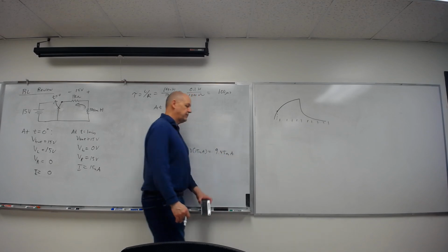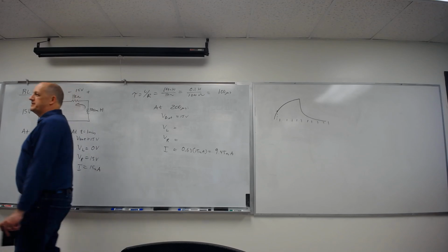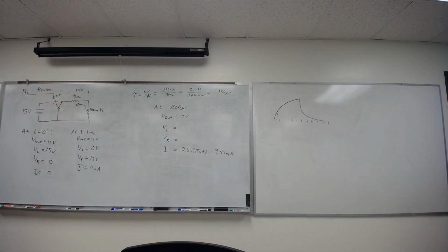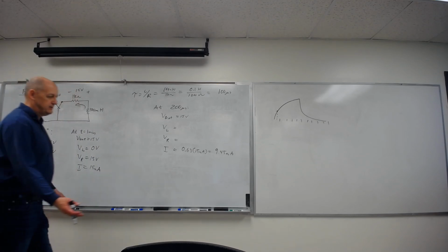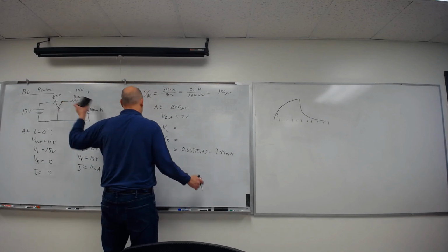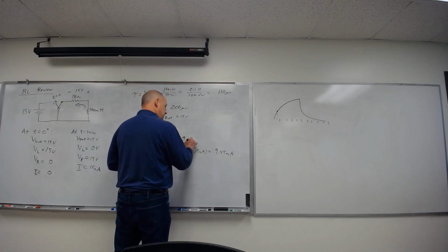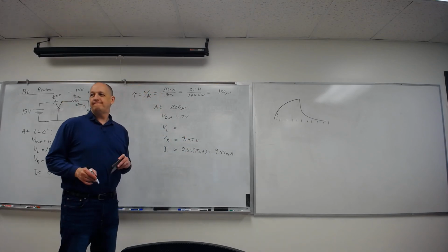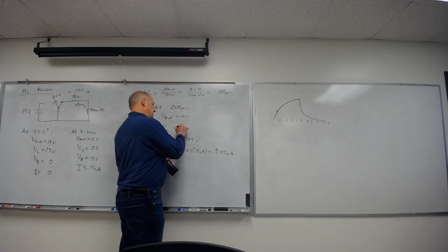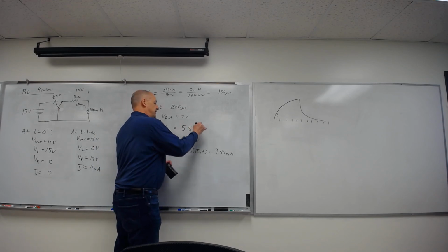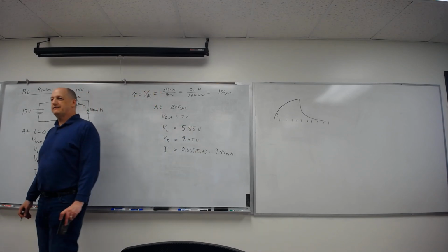So I've gone from 0 up to 9.45 milliamps. And now I can do Ohm's law, that times that. And up here, I'm going to have 5.55 volts. Just those two have to add to 15.